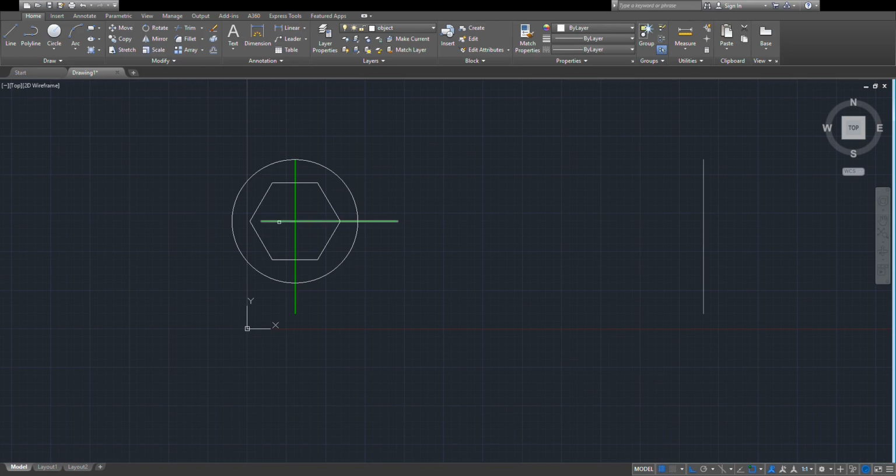And the horizontal line is actually 35 downwards, so we're going to offset it. Offset distance 35, select the object to offset, select this horizontal line, and then move downwards. So for move, we can just move it around, and also this one we can move around.